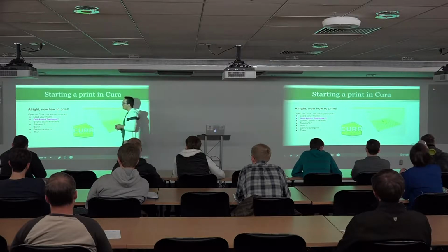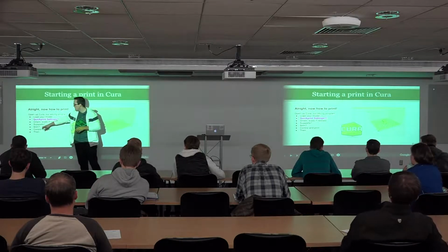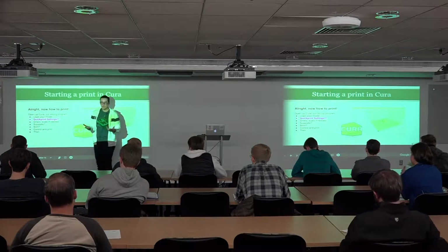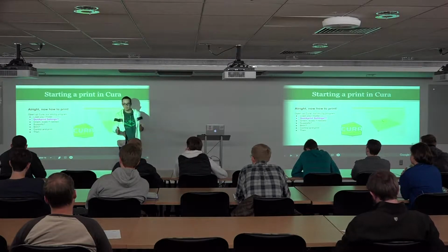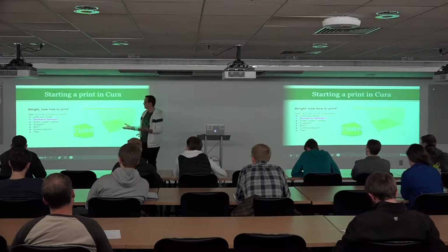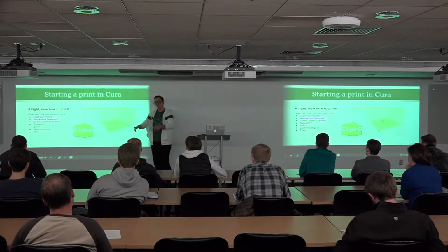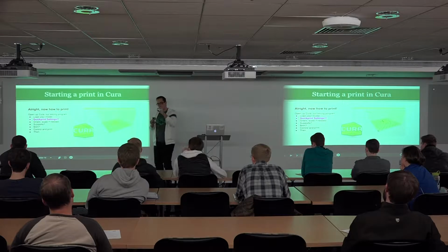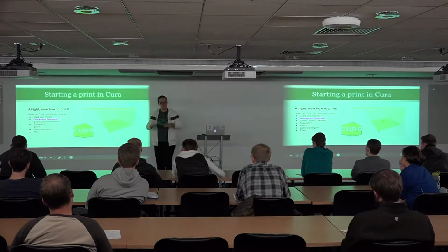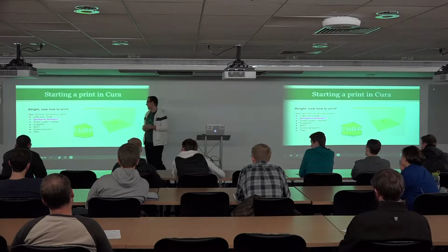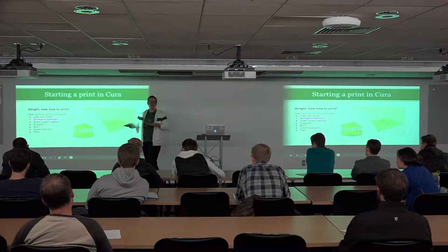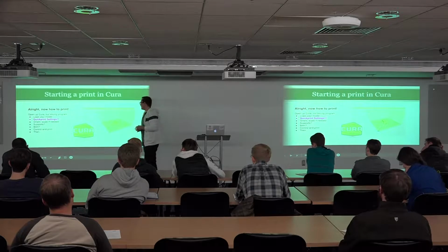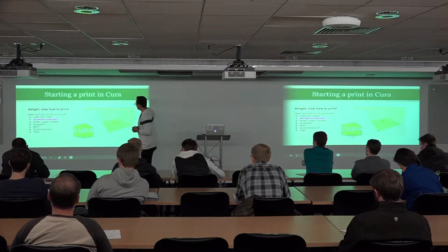Brim I mentioned because if you're printing with ABS, or you're doing just a long print or a big flat print with basically any material, if it's a big print on the bed, probably throw a brim on there. It just adds about a centimeter of material around the edge on the first layer just to make sure that it's going to stick down really nicely for the whole print. And so that's a useful tool to use.